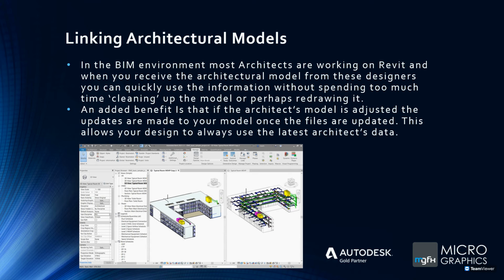If you're working on a project and there's an architect who uses maybe just AutoCAD or some other application that's just 2D, you can also import those 2D views simply as a 2D view, meaning that if you work in plan, you import his plan. If you work in elevation or section, you import his section or elevation, and then you just draw your ducts floating.